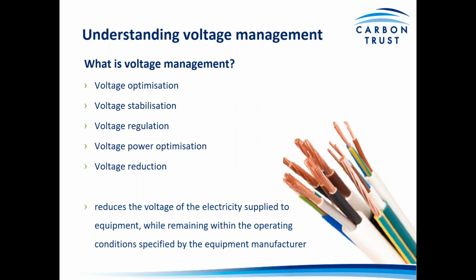But simply put, voltage management reduces the voltage of the electricity supplied to equipment that you have on site, which minimizes the consumption of that equipment whilst making sure that it still remains within the operating conditions that have been specified by the equipment manufacturer.